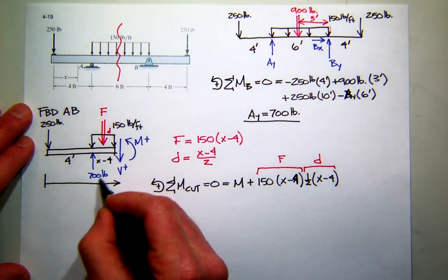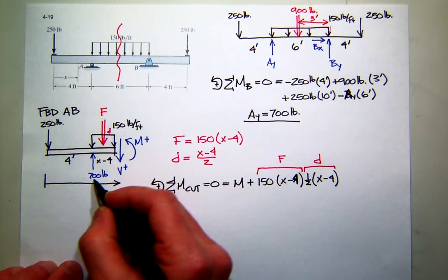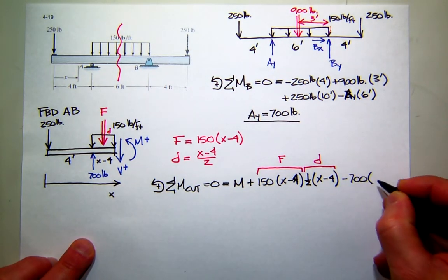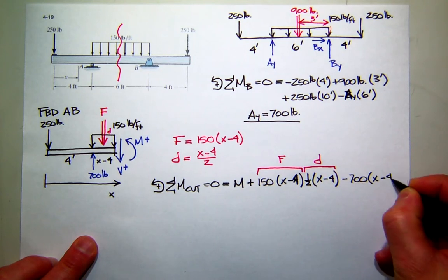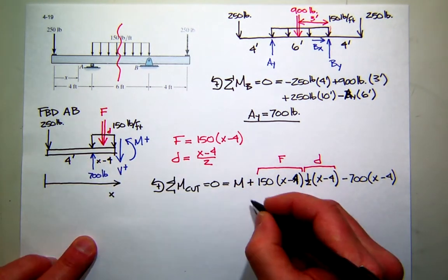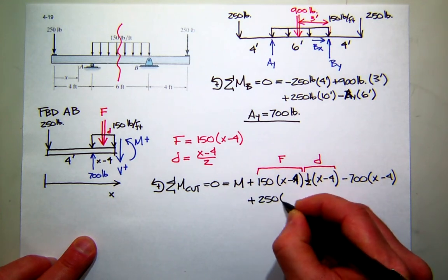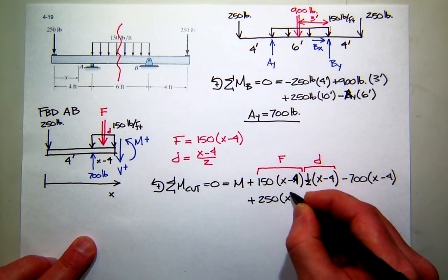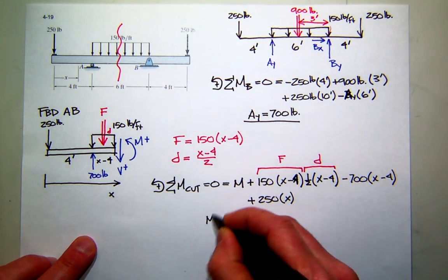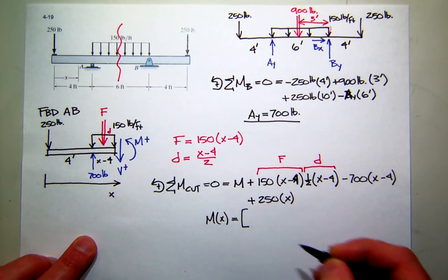Then I have my 700-pound force. What kind of moment does it create? Negative. So negative 700, and what's its moment arm? X minus 4. Then all the way out to the end, this 250 creates positive moment and has a moment arm of X. So now we'll just collect all the terms. So our moment as a function of X is equal to...